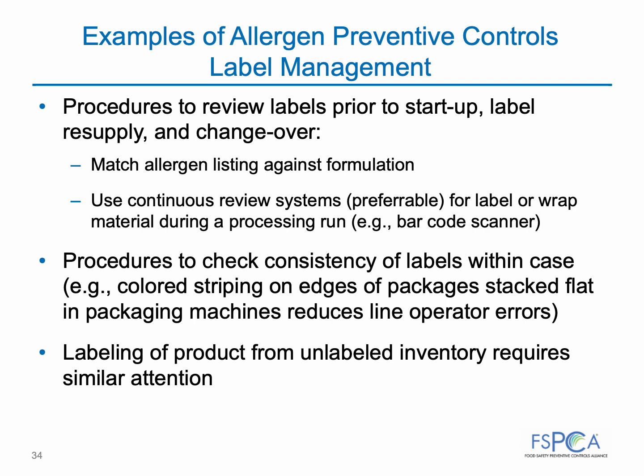Check packaging film labels for accuracy, e.g., by comparing the label to the formulation or recipe of the product being produced before the label roll is placed on the packaging machine. For on-site computer-generated labels, verify that the correct electronic file is applied for each label, and have a system that lets only authorized personnel edit electronic label files.